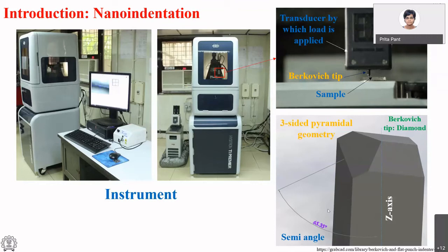The reason I want to show you a schematic of a perfect tip is that we will address the issue that the tips that we buy from the market are not perfect to begin with, and as we use them, this end of the tip, which is doing the poking and indenting, gets worn out. So we need to correct for those effects when we analyze the data.